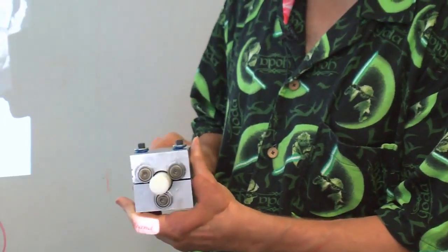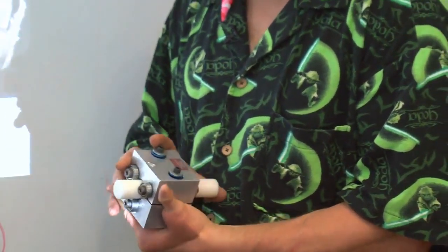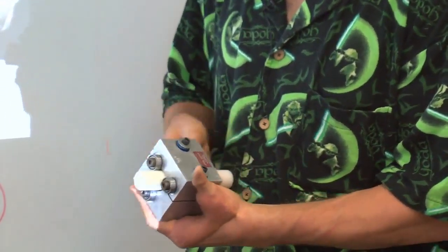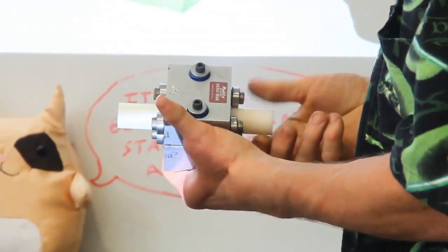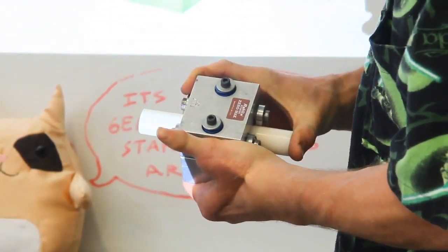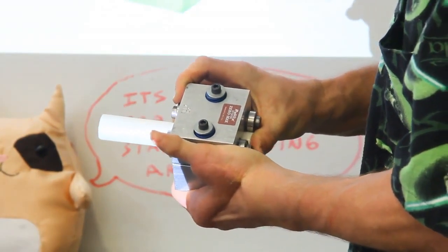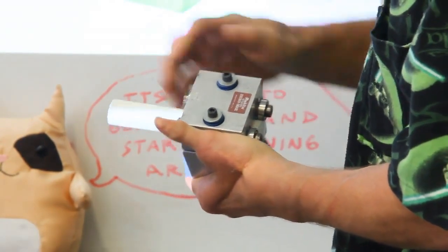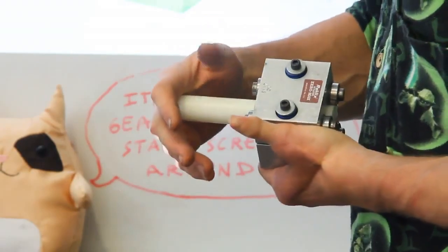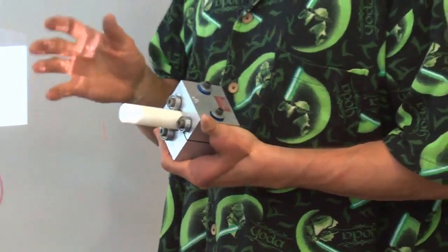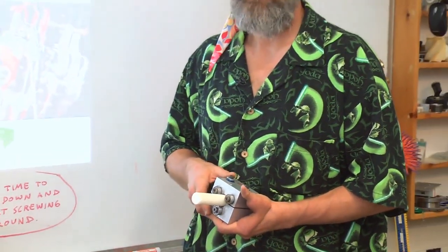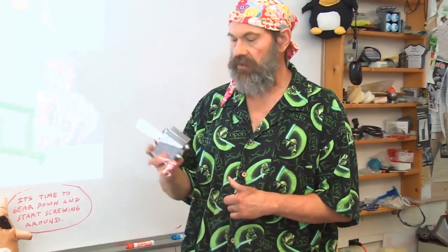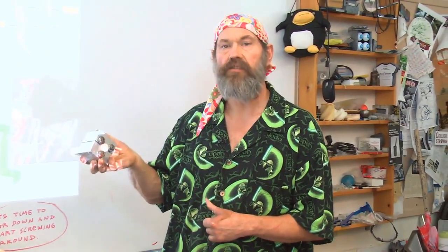This one actually is set fairly large. This device was designed originally so I could have a lead on a smooth shaft, but it also has a safety feature that you see it can be slid if the screw comes to the end of travel and keeps turning. With a regular screw thread, which is a positive mechanical engagement, something is going to break or stall. So this is a very, very nifty device to have in your design toolkit.